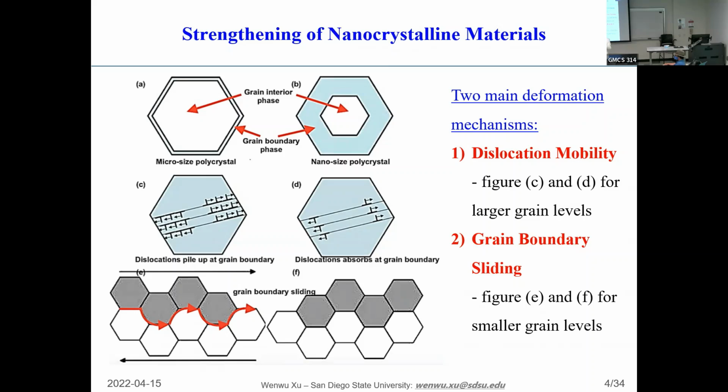The more plastic deformation we have in the metal, the more dislocation defects are going to be generated. This dislocation is going to move across the crystal or the grain of the material during the deformation. And this motion of all sorts of different kinds of dislocations will start to accumulate at the grain boundary. Eventually, when this accumulation is significant enough, it's going to accumulate lots of stress at that region, and later it is going to become the nucleation of a crack inside that region, and eventually cause the failure of the metal with a sufficient amount of plastic deformation.